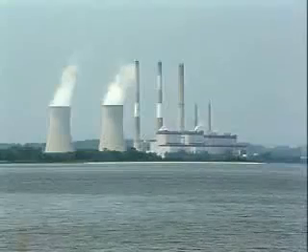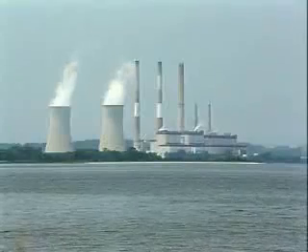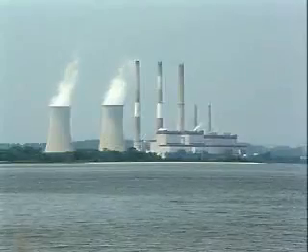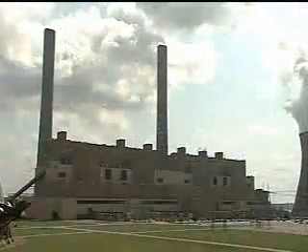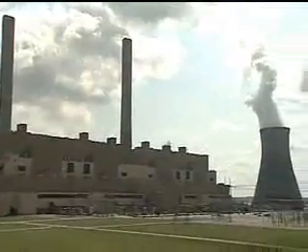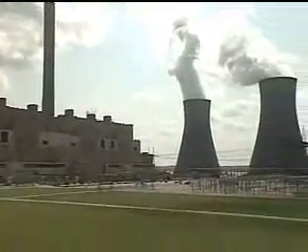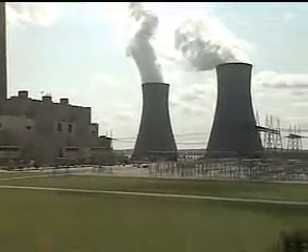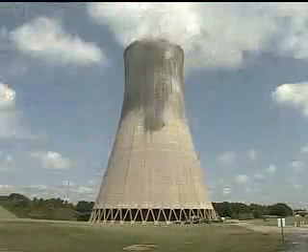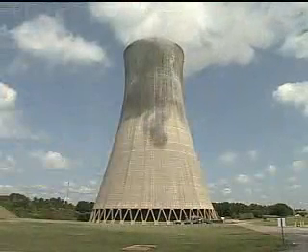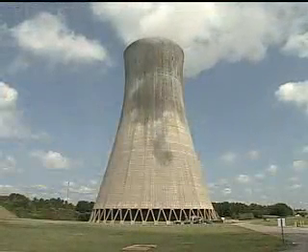Not all power plants are located in an area where there is an adequate water source, such as a lake or a river. For those types of plants and for plants that have to comply with strict environmental regulations, the cooling water is kept within the circulating water system to be recirculated. In order for this type of system to function, a cooling tower is needed.